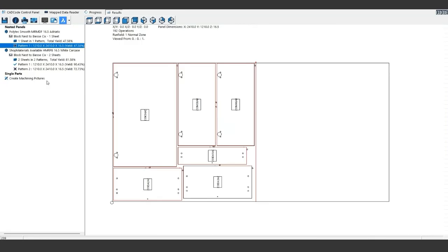And we've got different nesting strategies in terms of trying to utilize, either make sure you use that offcut in the next job, or if I have this offcut available and you do get a better yield using it, do that. But if not, just get the best yield you can from the board that we've got. Because what we find with offcuts is you use an offcut to make an offcut, and there's a couple of different ways you can go about doing them.